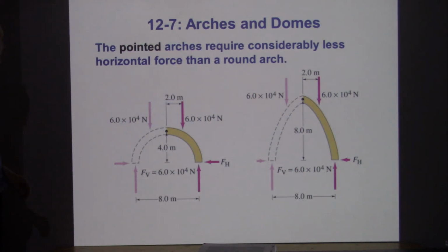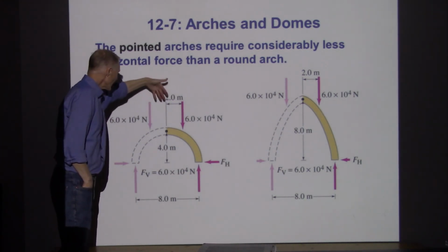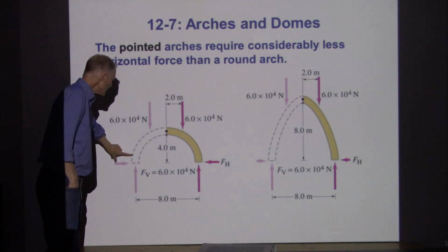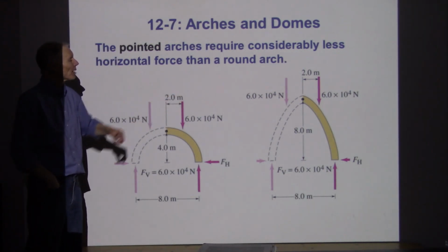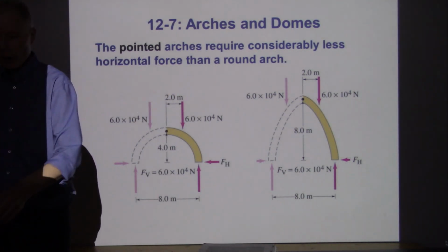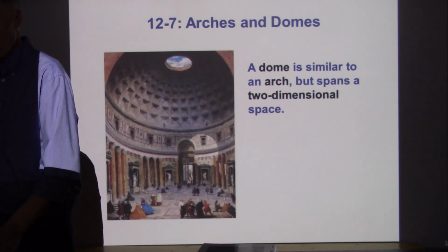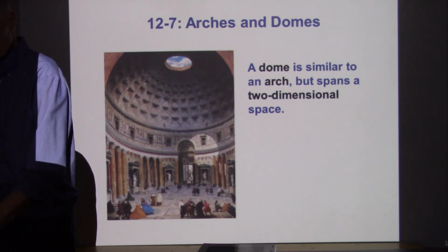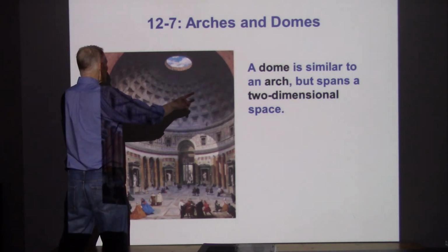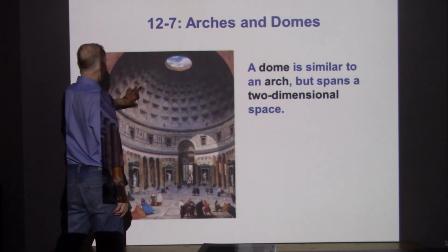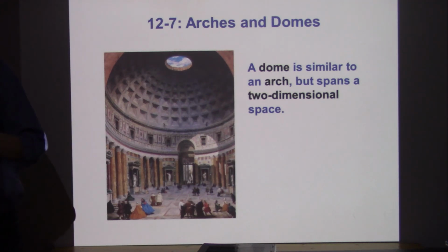Also, they're showing here some of the forces, again just kind of informational. If we have a lot of force acting here, we're going to need some horizontal forces to hold these structures into place. What we can do is do better if we change the shape. A rounded arch works better. Here we are. Here's an enormous dome. And you can imagine that once you get an enormous dome built like this, there are going to be large horizontal forces from all of these blocks pushing against each other. So everything here is under compression.